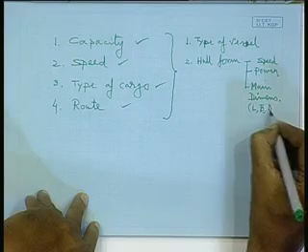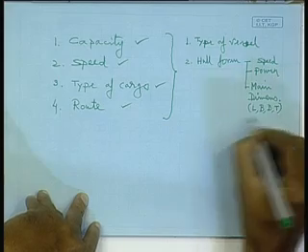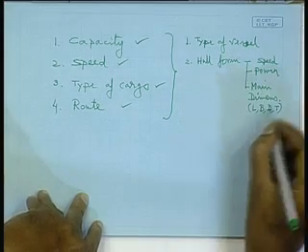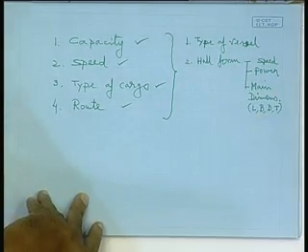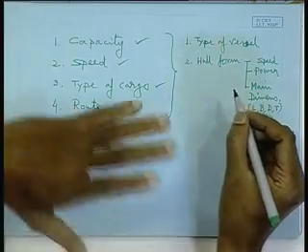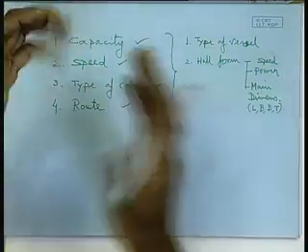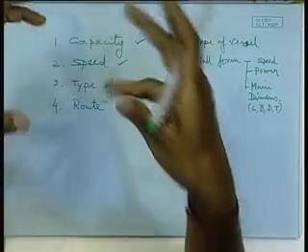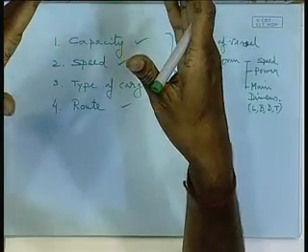In fact, first you will come to the main dimensions. Main dimensions are nothing but what? Length, breadth, depth and draft, right. Then when we come to the hull form, they are basically the form coefficients and the hull lines, block coefficient, prismatic coefficient, all those things, and how the lines should be.